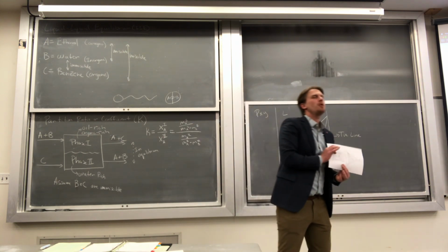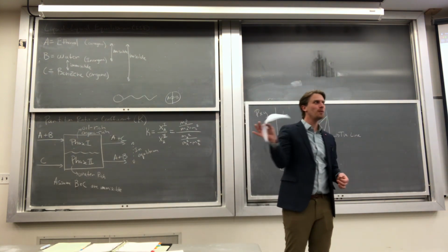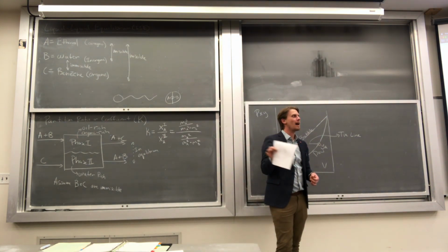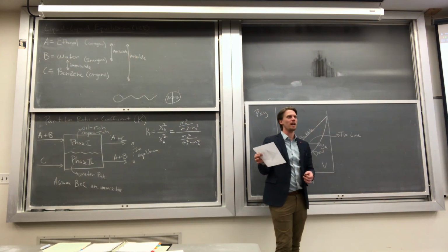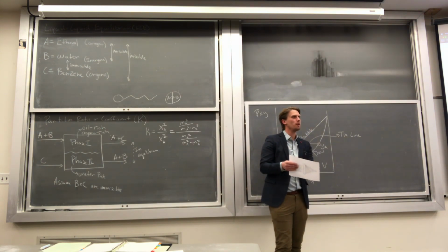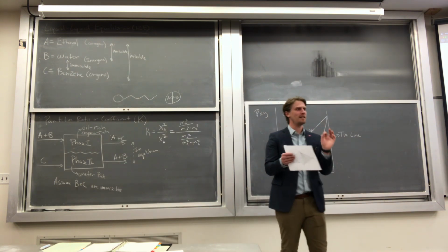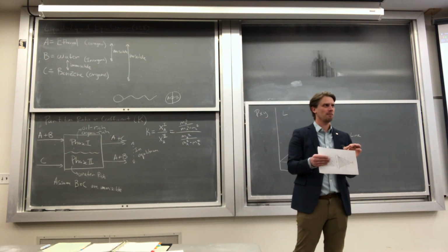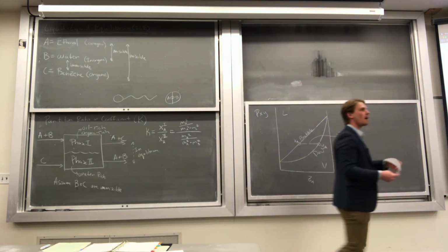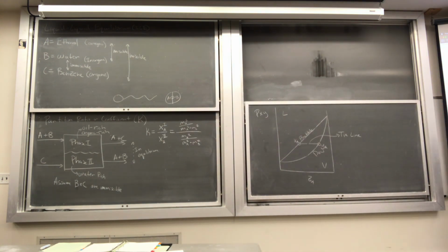So there's going to be some degree of subjectivity in reading these diagrams. I am cognizant of that when we do exams and homework problems. But getting a ruler out and estimating what percentage it is between those lines gives you a way to do that. Does that make sense? But make sure they add up to 100. There may be some slight differences in people's answers. Okay? So that would be the composition of the C-rich phase.